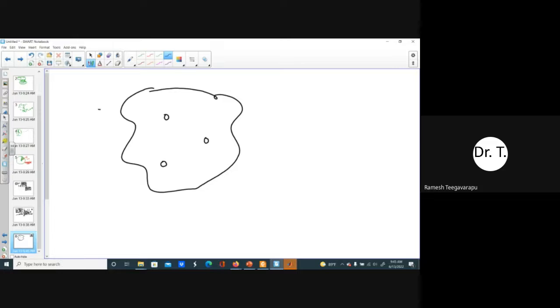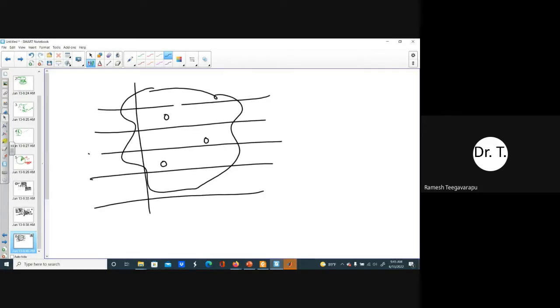Whereas radar, where I'm putting a Cartesian grid here, is actually getting rainfall in every single grid cell on top of the watershed. Therefore, radar data is extremely beneficial for distributed hydrologic modeling. First of all, radar data captures extremes which were missed by rain gauges.